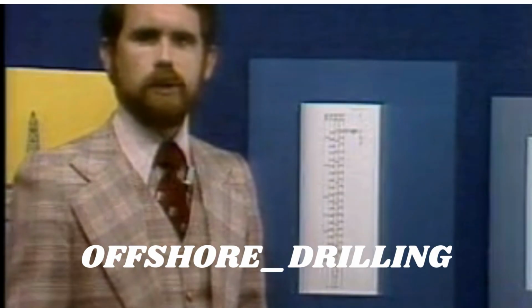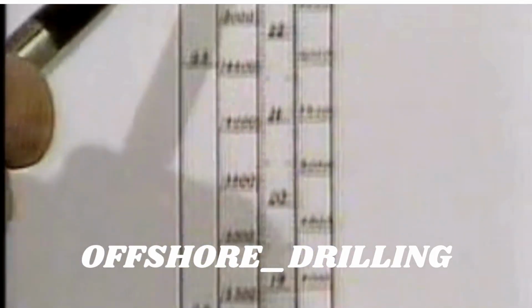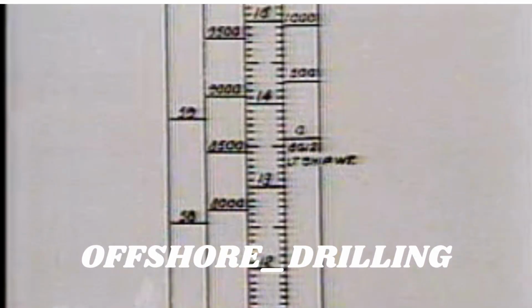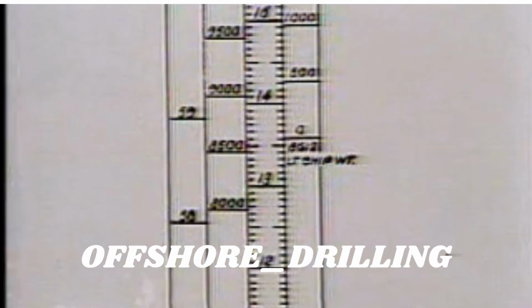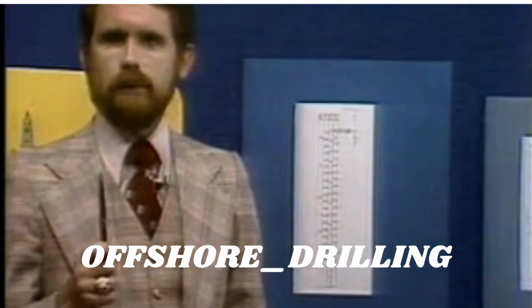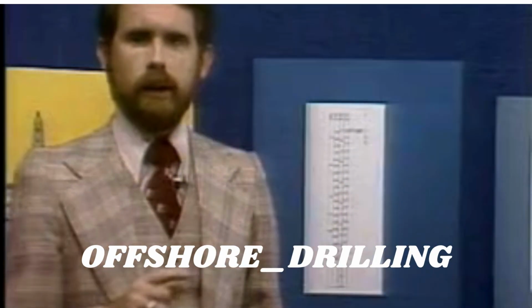Besides the information just mentioned, you can see that the graph also shows us the light draft and displacement and the maximum summer load line, which you will notice is to the top of the line through the load line circle. The light draft is the draft with the ship completely empty, no cargo, crew, fuel, stores, or water on board. Deadweight at light draft equals 0. The light draft displacement is always the difference between deadweight and displacement at any other draft.